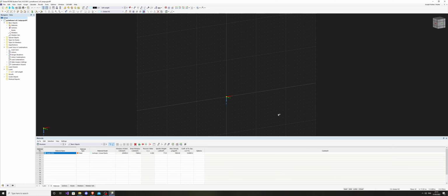Yeah, there we go. It's Control and the middle mouse button, hold on to it and just pan around. So this is normal panning, just holding the middle mouse, the zoom button. But Control and the middle mouse helps you rotate it.